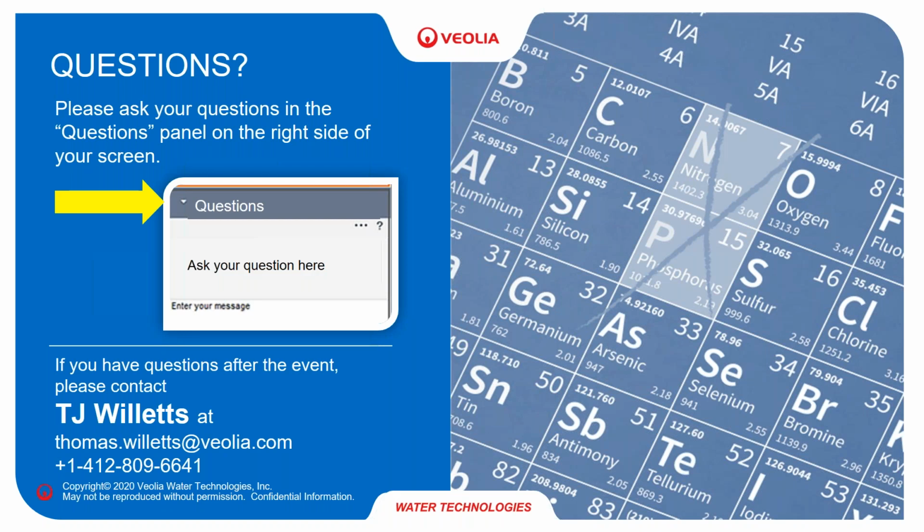Or if your permit states TKN, or ammonia and nitrate nitrite at the same time, which effectively is the same thing. Basically, they're telling you we cannot receive this amount of ammonia, neither can we receive this nitrate nitrite. So all that is left for me is to remove the nitrogen fully into its elemental form, which is nitrogen gas, which is going to fly out from your basin, and go through the full nitrification, denitrification step, which needs to be very carefully designed.